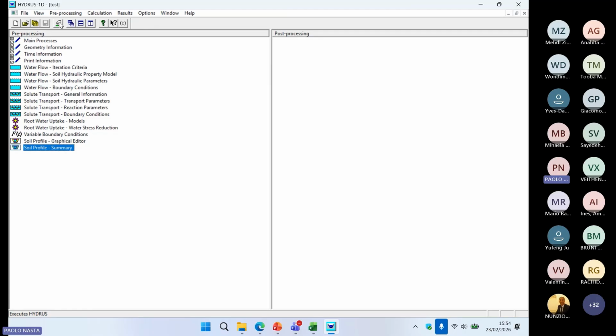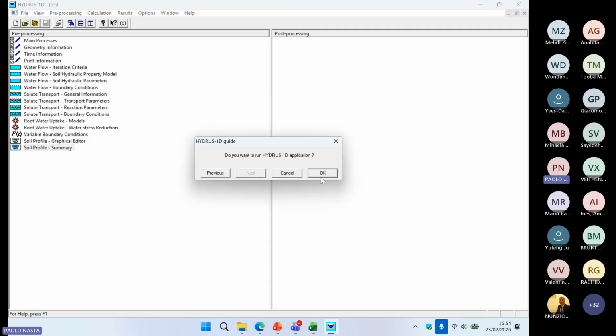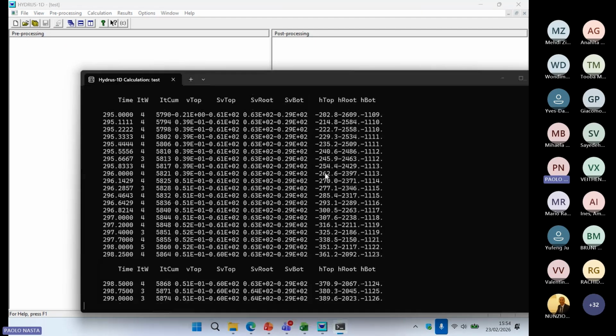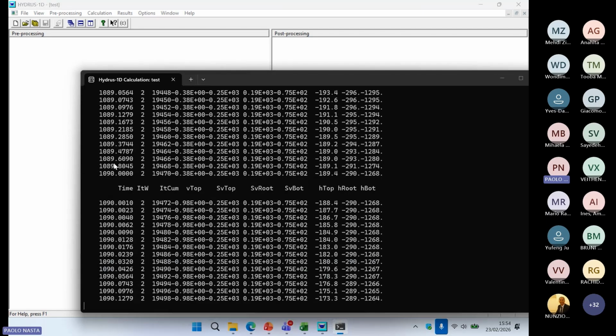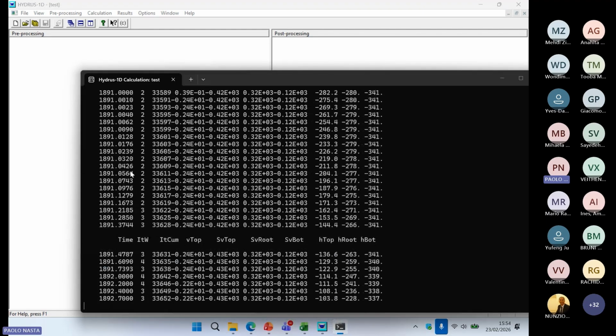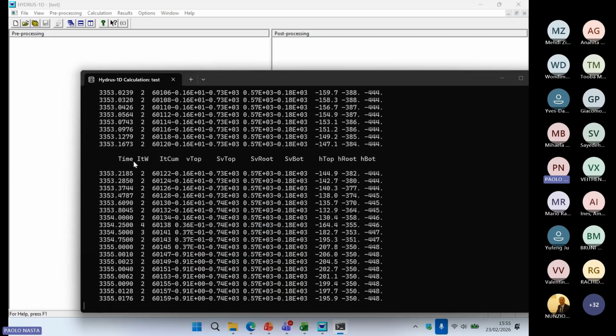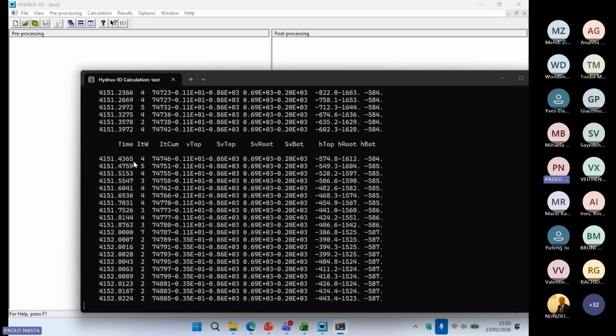You have to check if the upper boundary conditions seem okay, the units are okay, and the precipitation and the evapotranspiration are reasonable and realistic. So you need to check several things, but if you press the button and click OK, you see that the model runs every day until 5,113 days. So far it runs smoothly.